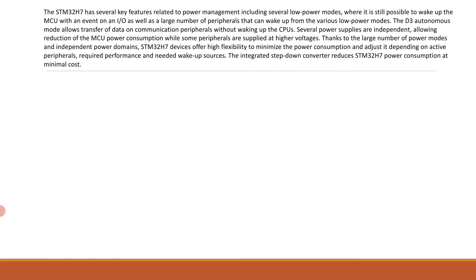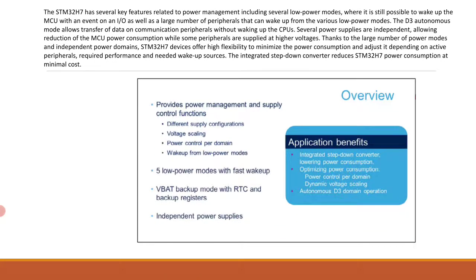STM32H7 has several key features related to power management, including several low power modes where it is still possible to wake up the MCU with an event on an IO, as well as a large number of peripherals that can wake up from the various low power modes.